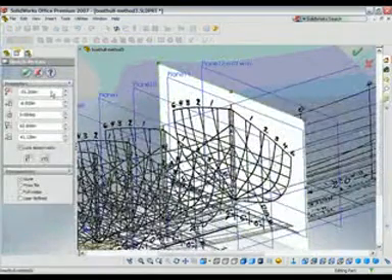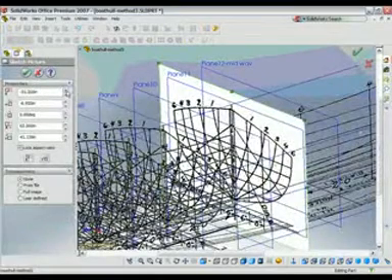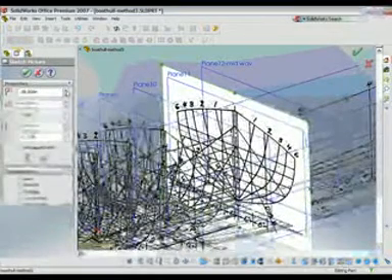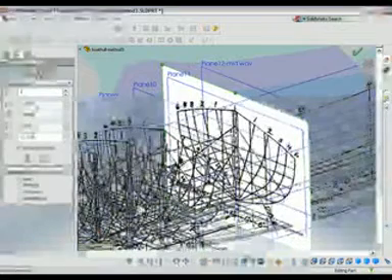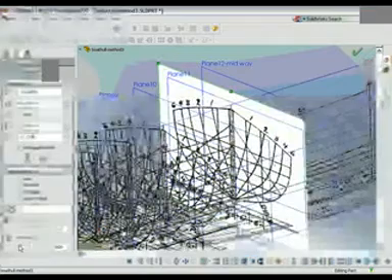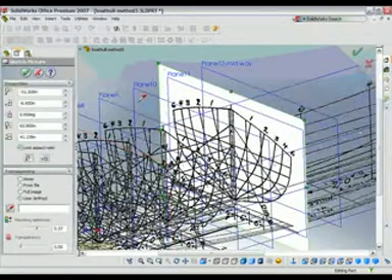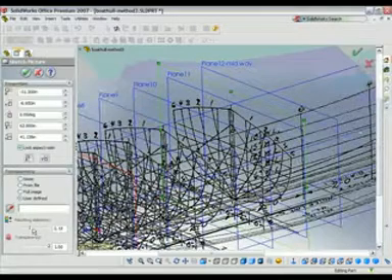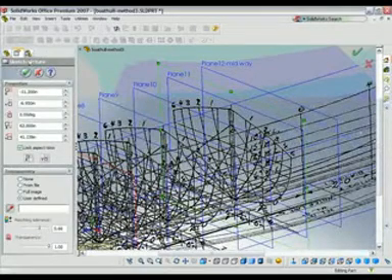Let's turn off the transparency. You see that there's drag handles that we can drag those around with, but also we can input numerically the X, Y, rotate, and scale values. Since each of these is identical, I know these numbers and I entered them for all of them. With the transparency, I assigned a user transparency of the white surround, and then used that white as the part of the sketch I wanted to show transparent.